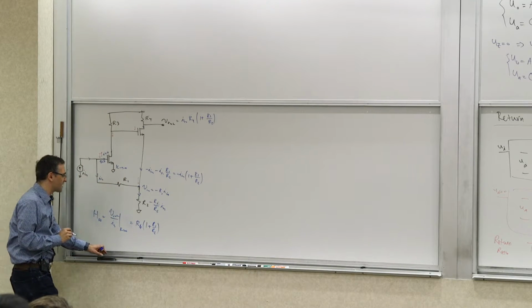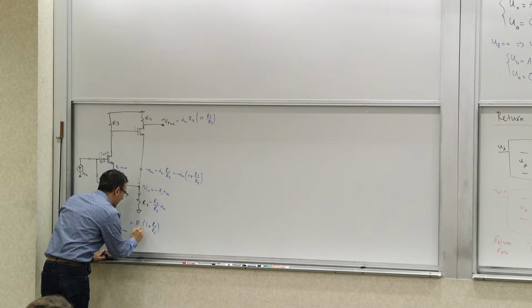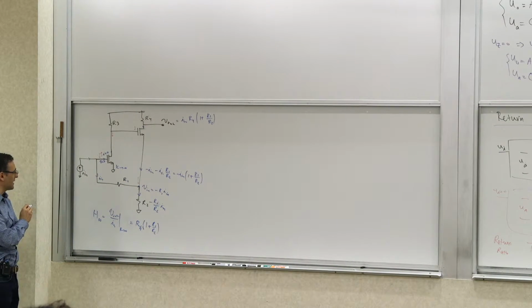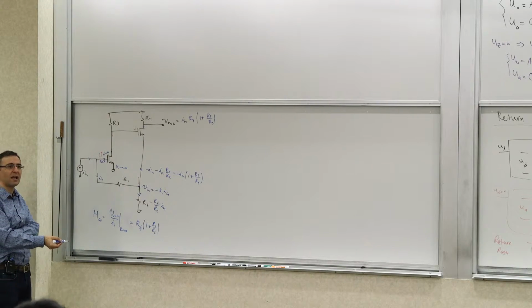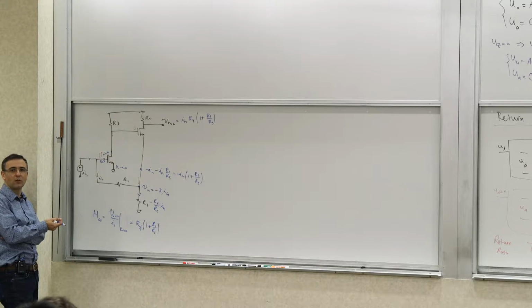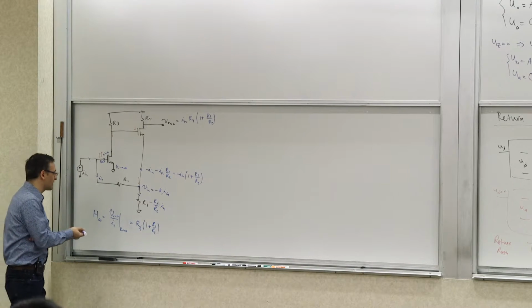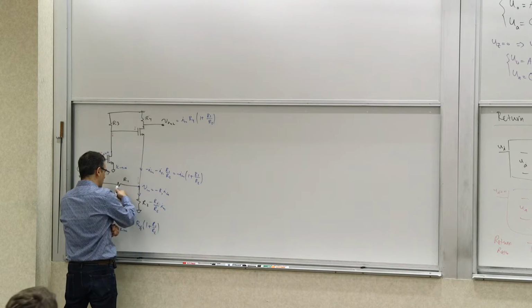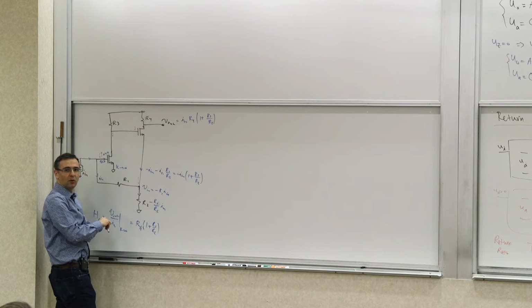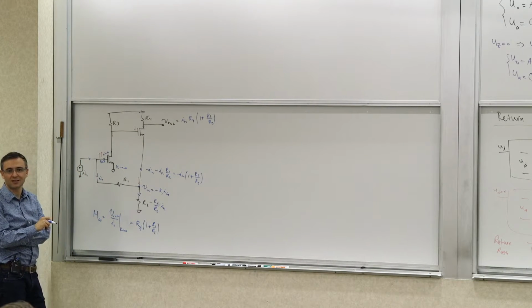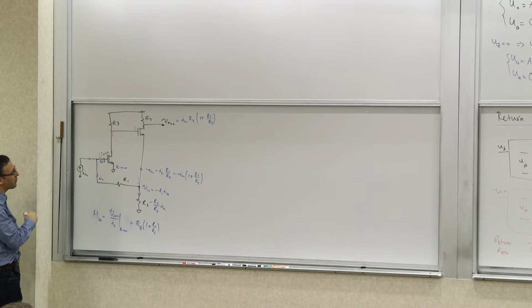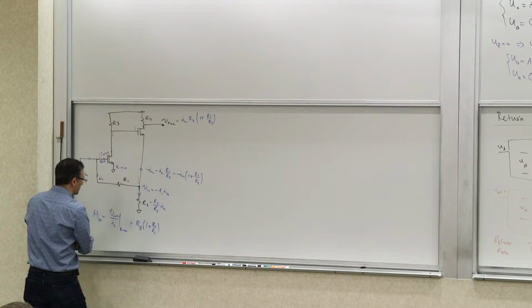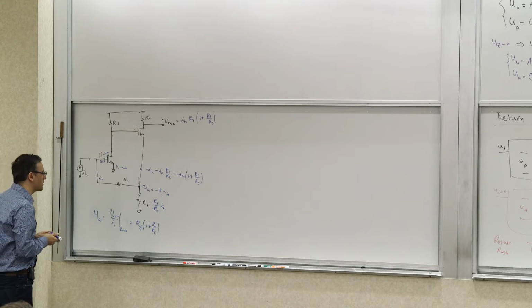So this is what we calculated last time, right? We did calculate this. I'm just redoing it quickly. This is the asymptotic transfer function. This is what the ideal feedback system would do. So if you need a transresistance of 5 kilo ohm, you can make this, for example, R4 1 kilo ohm, and make this ratio of R1 to R2 4 kilo ohm and 1 kilo ohm, if you're designing very quickly, the 5-second design exercise, right? So now we want to see how close or how far it is from the actual answer, the correct exact transfer function. Okay, so to do that, we need to calculate the return ratio.